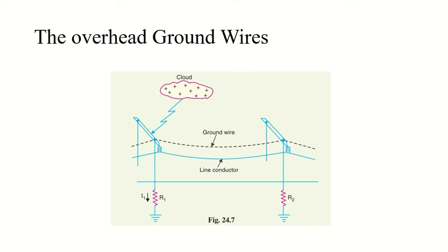Now, what are the disadvantages? So first one is the cost, because you need the whole ground wire, you need to ground it through the poles, so its cost is very high. Second one, there is a possibility of its breaking and falling across the line conductor, thereby causing a short circuit of faults. And this objection has been greatly eliminated by the galvanized stranded steel conductors as ground wires. This provides sufficient strength to the ground wire as well because of these galvanized stranded steel conductors, right?